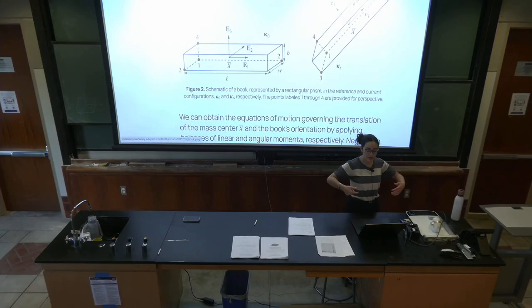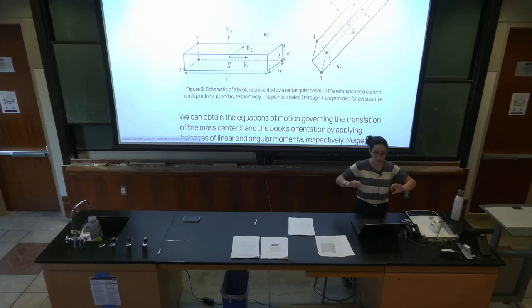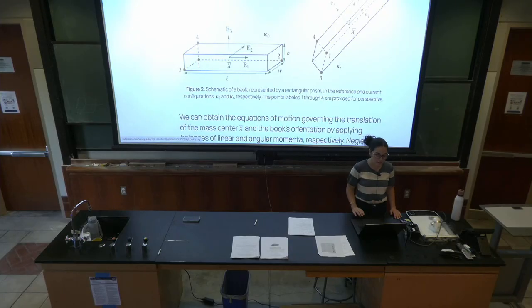And so what happens is that if I rotate about E2, the intermediate axis of rotation, that's when I'm going to see the instability. What does an instability mean? It means that I'm giving the phone or the shape an initial orientation, initial rotation, and the motion is stable if it remains close to the initial rotation I gave it. And it's unstable when it goes far away from the initial conditions that I gave it.